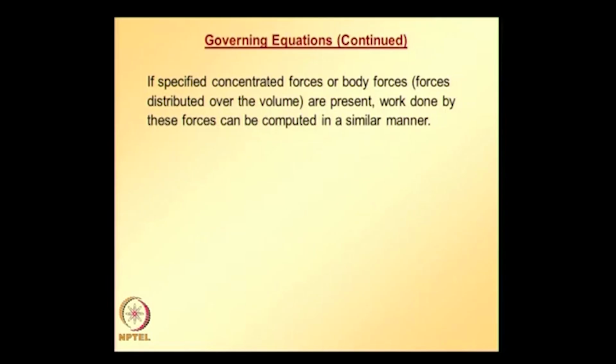Here, as a part of this 3 dimensional elastic problems, we are going to look at 4 node tetrahedral element, which is basically a linear element for solving 3 dimensional elastic problems, and also we look at 8 node linear solid element, commonly known as brick element, and 20 node solid element with curved edges.